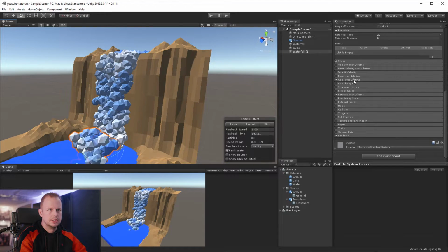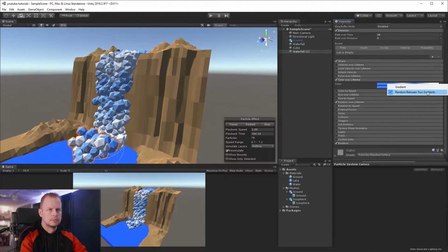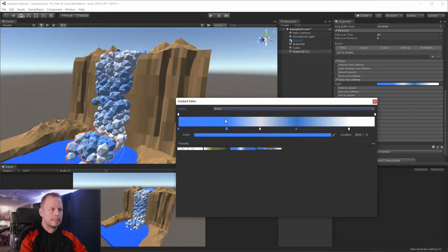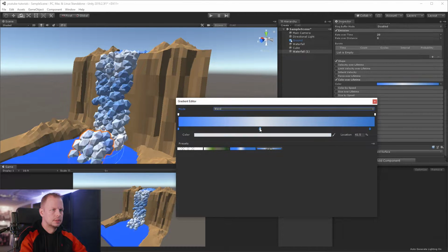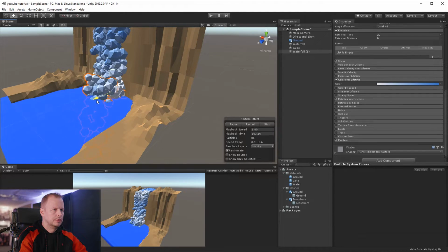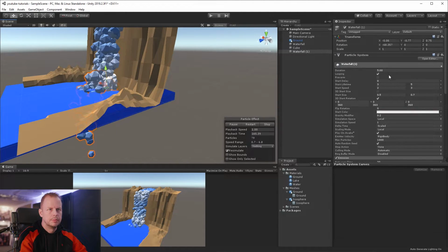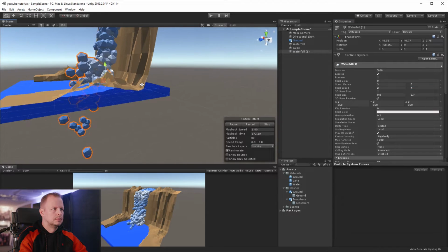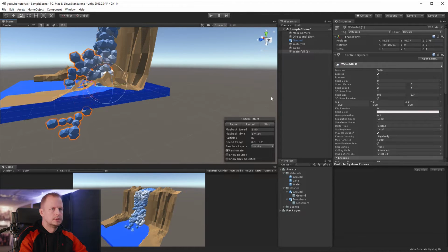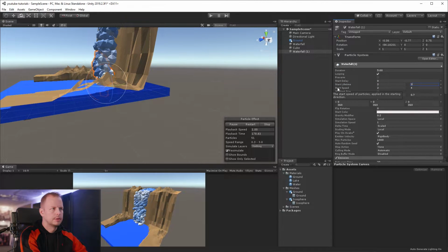And then let's switch these to all white. And then into blue actually as it ends its lifetime there. Take this one away. W, move it in a little bit. Let's shoot them up a little bit higher, even still, start speed between 2 and 4. Rotate it a little bit again. And then we can shorten their lifetime down to between 2 and 3 only.